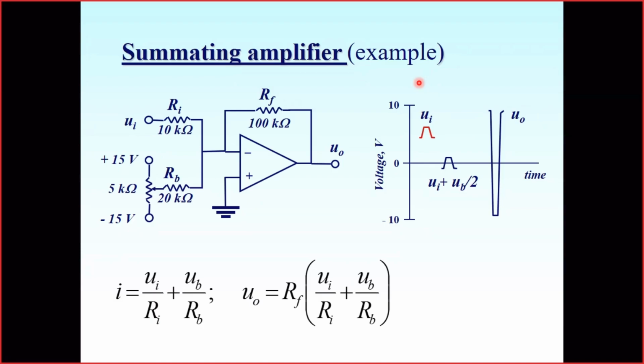So what I could do is extract this base, the constant voltage, from my signal. When I extract it, the resulting signal looks like this. And now I may use quite a high gain to amplify it. So here is just an example. There is the initial signal. Here I subtracted this constant component before amplification, and here I amplify it with an inverting amplifier.